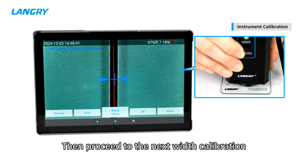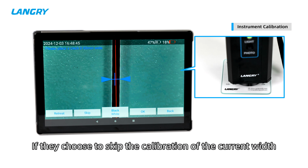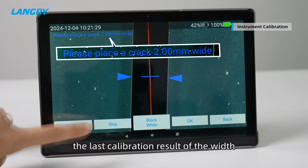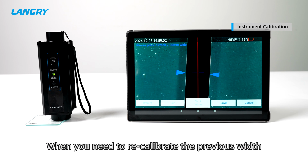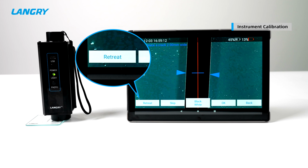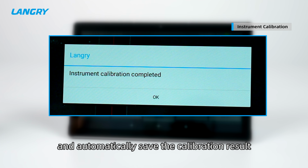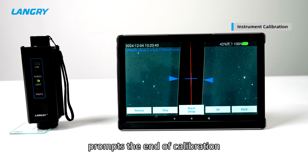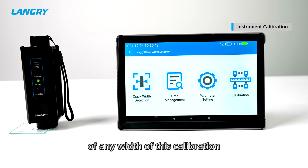Then proceed to the next width calibration. Users can calibrate according to their needs. If they choose to skip the calibration of the current width, the system will continue to use the last calibration result of the width. When you need to recalibrate the previous width, you can choose Retreat to calibrate again. After the calibration is completed, the system will prompt and automatically save the calibration result. Note, if you click back before the system prompts the end of calibration, the system won't save the calibration results of any width of this calibration.